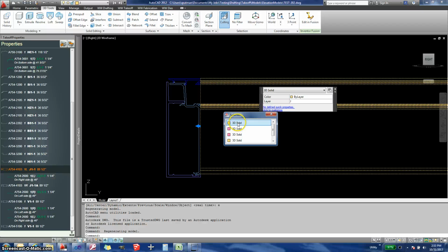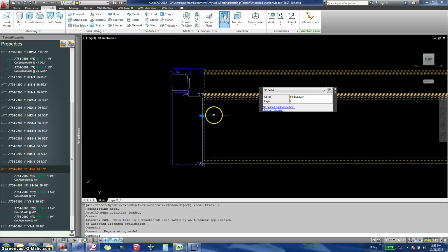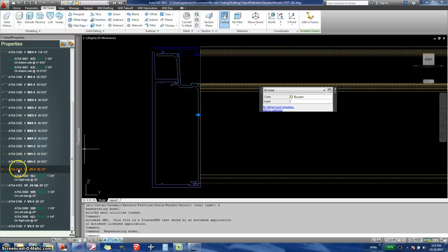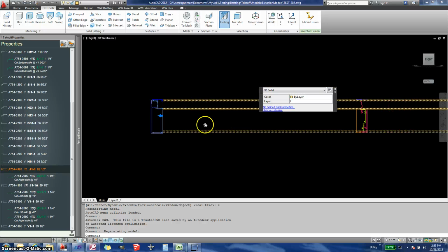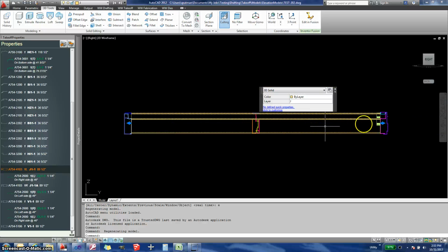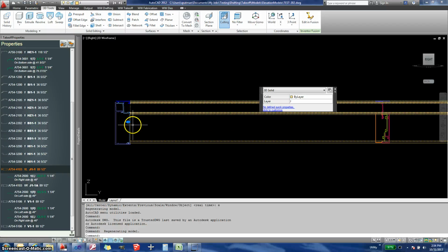So to fix this, you can go back to the data, or you can fix it right here in the BIM model, which is really nice because you can see exactly what you're doing. I'm going to start off by clicking one of my jambs, and automatically what appears are grips in AutoCAD in blue, and they look like arrows.